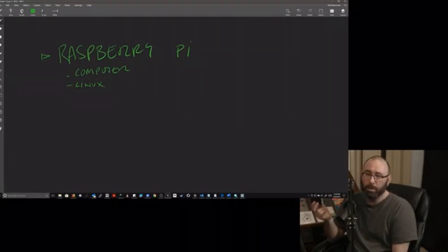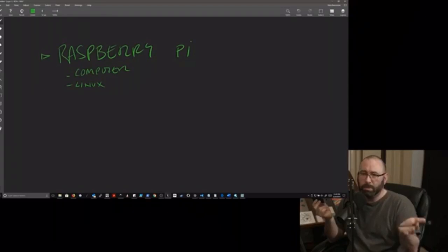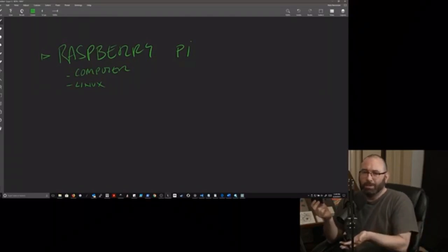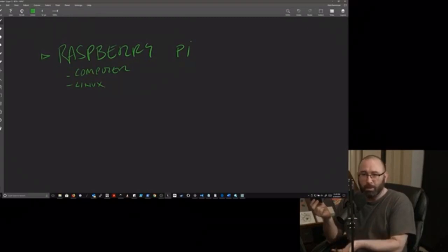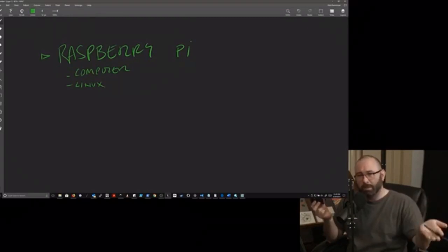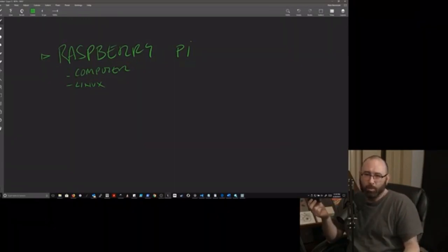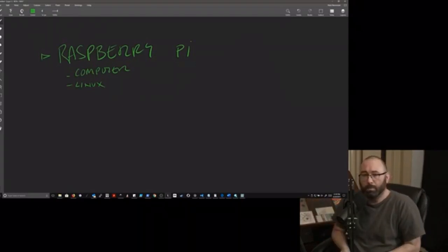So if we're looking at a 12-volt system, basically we can convert that over to 10 volts really easily. So basically that's 1 amp, right? If it's 5 volts, 2 amps, it's going to be 10 volts, 1 amp, right? And then because we're at 12 volts, it's going to be a little bit less than that. So we're probably looking at like 0.8 amps at max, 0.85, something around that range. So very, very low power draw, and that's at maximum, right?